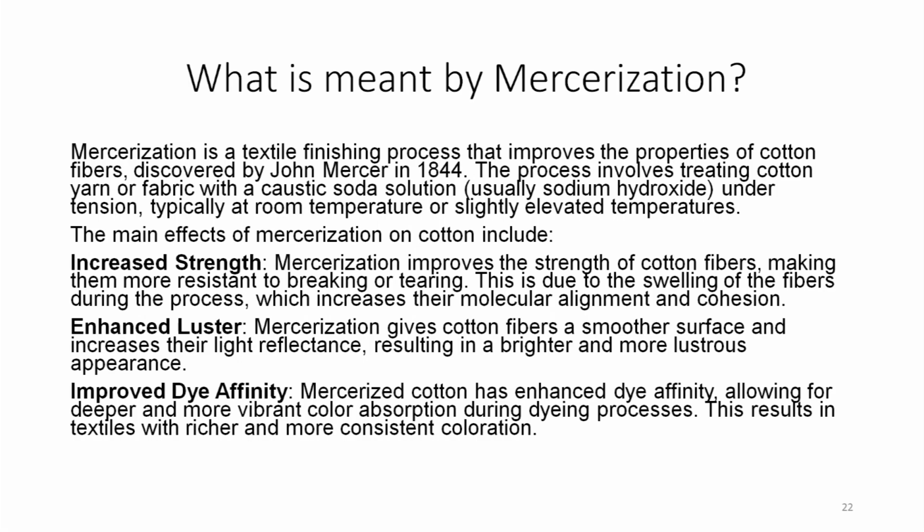The main effect of mercerization on cotton includes increased strength. Mercerization improves the strength of cotton fibers, making them more resistant to breaking or tearing. This is due to the swelling of the fibers during the process, which increases their molecular alignment and cohesion. Increased luster.